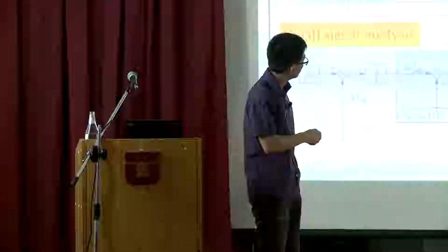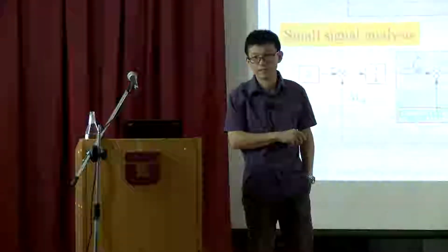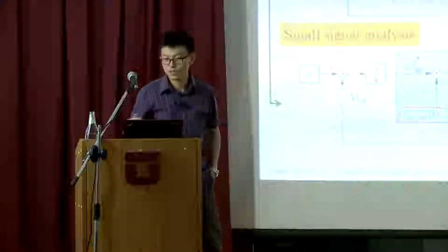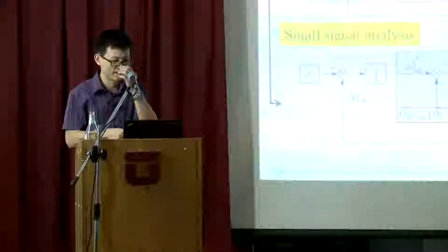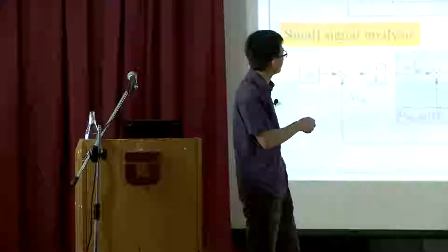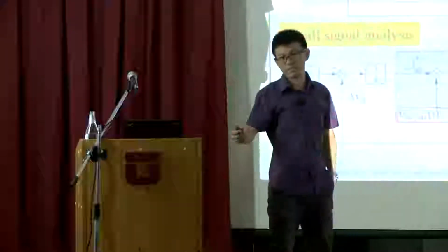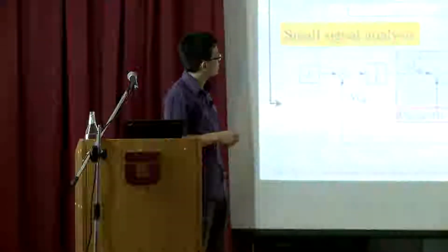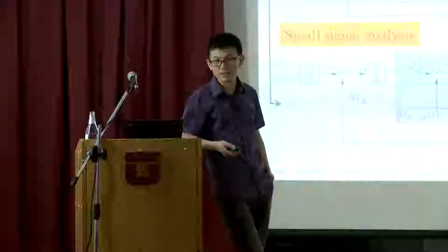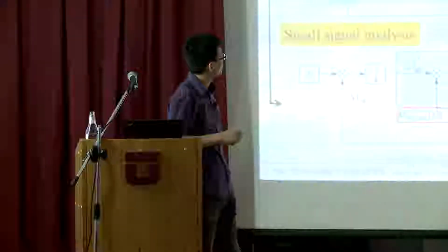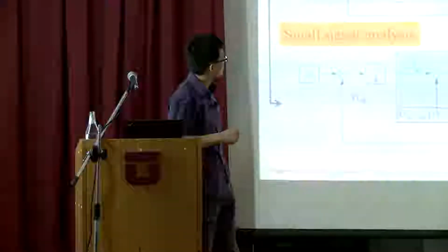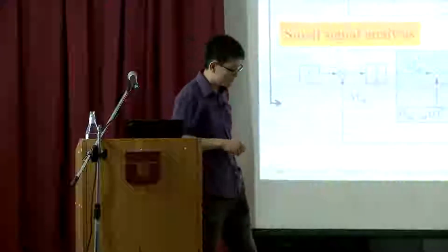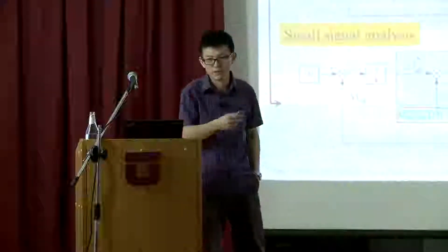This is the total active power. If you understand the machine well, you should understand this. But if you don't understand, essentially, from IQ, I can derive my active power. Active power divided by VDC is the current IDC. So this is the whole loop. You go from IQ to get IDC. For IDC, you can feed back to the droop.